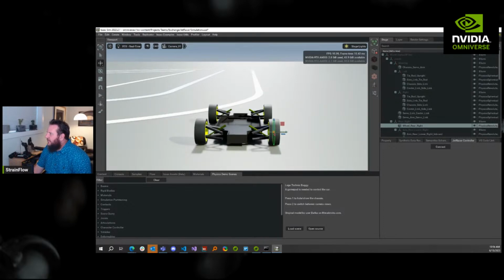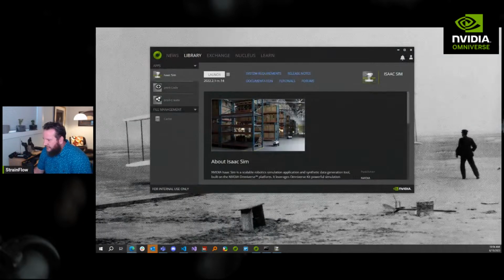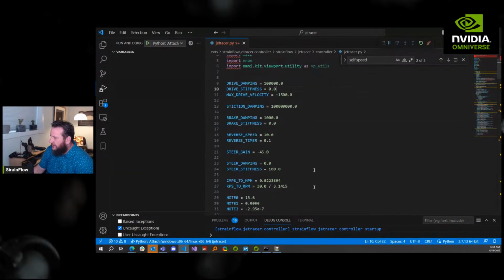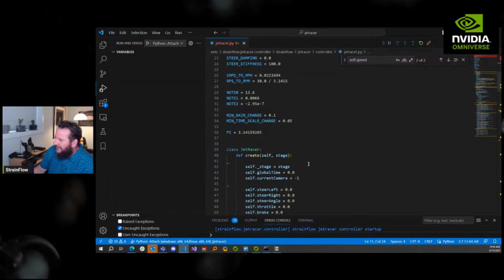And we're trying to work that out all the way, you know? I'm just kind of keeping my eye out for things that might be causing that. One of those I thought might be that. I thought that was a max speed, but really it was a minimum speed. And we can crank this drive velocity up, but like I said, it starts to make those wheels spin instead of getting traction, and then they get really bouncy and things get wild.